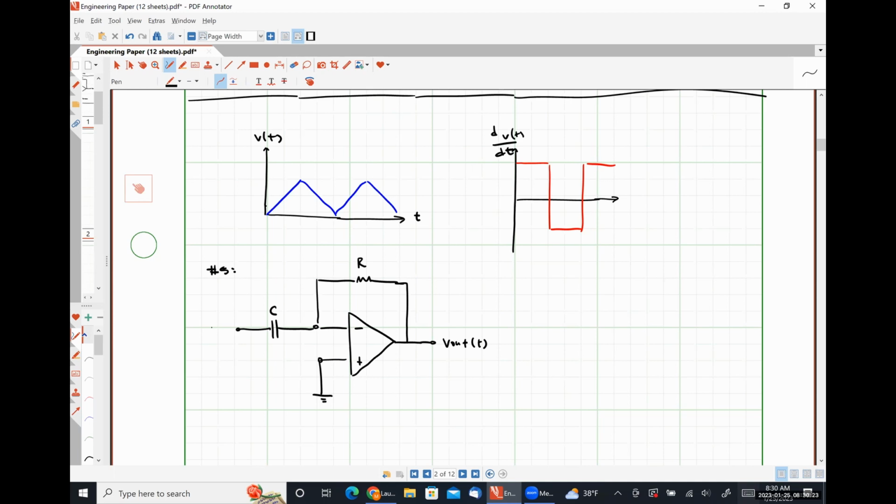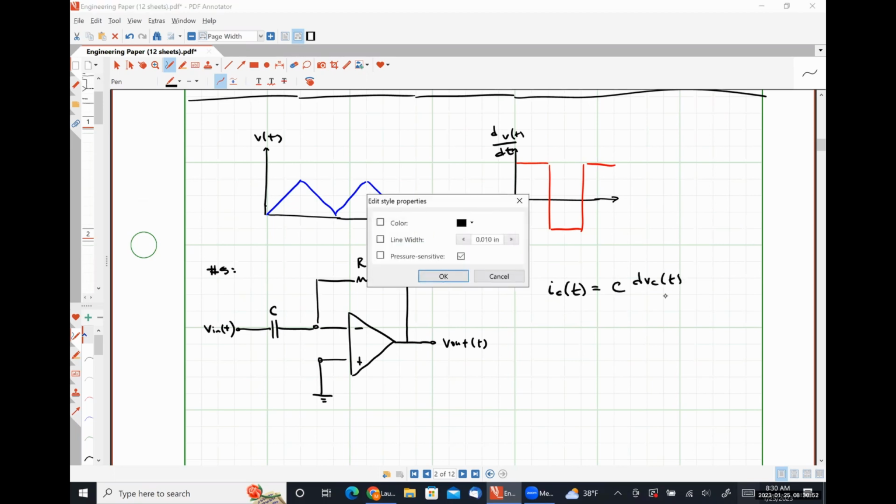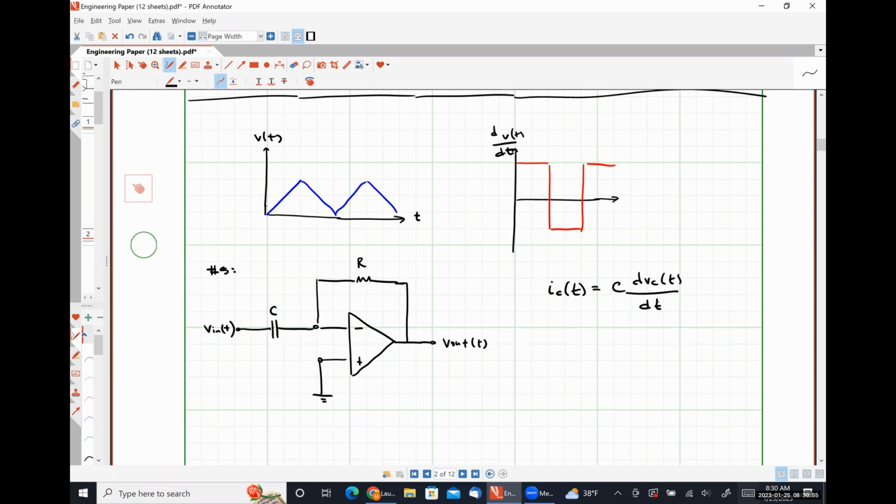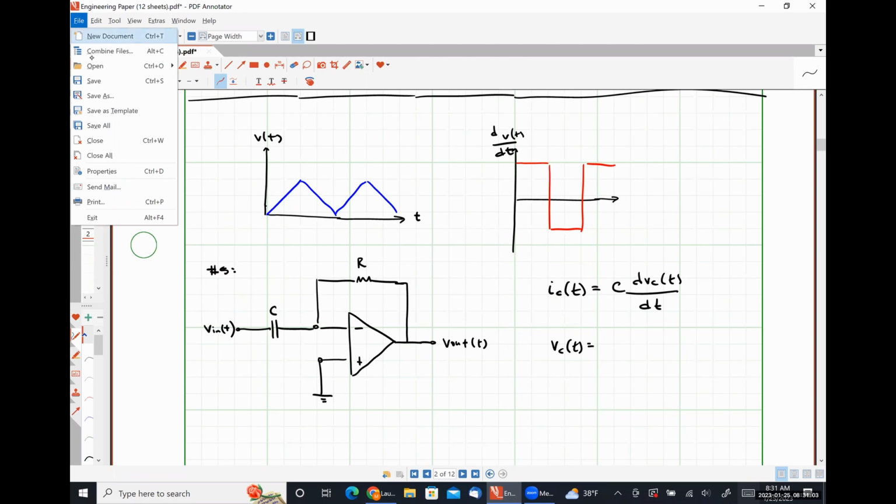C between our non-inverting input terminal and our input voltage. So because we have a capacitor in here, I'm going to remind you guys of our capacitor voltage and current relationships. So the current through a capacitor, IC(t), is equal to C dV by dt. And the voltage drop across the capacitor is 1 over, sorry, let me save this and restart this program, or it's going to keep giving me that annoying error.